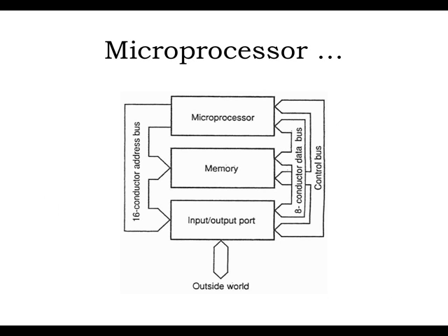Now the address bus means those are all the connections of 16 lines. So what does it mean? It means that all the memory locations have an address. Each of those has an address. What do you mean by address? Let's say you have some memory locations. These are memory locations. This has an address which is, let's say, 0000. So what will be the address of the next one?